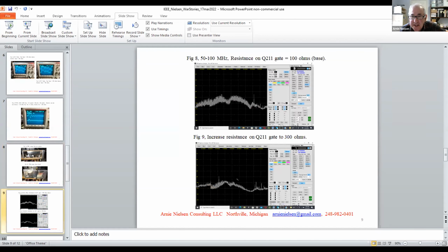And here's the results from my trusty old RSP-1A that we talked about a little earlier with Karen. And you can see there's a pretty big difference in the emissions. So that was a zero cost fix, and it didn't cause any excess heating. I was surprised to see that.